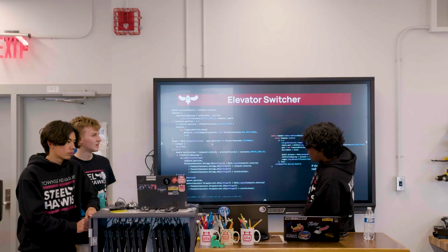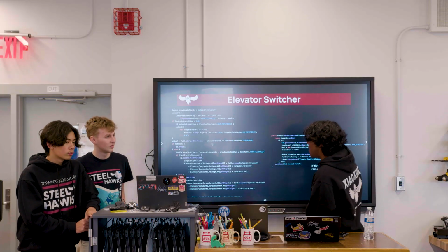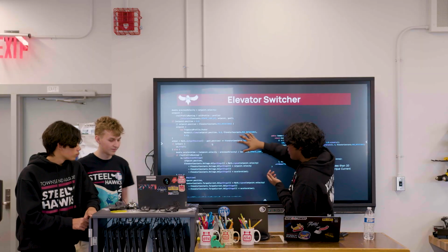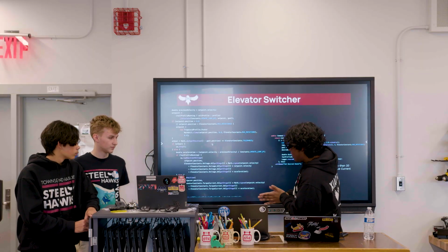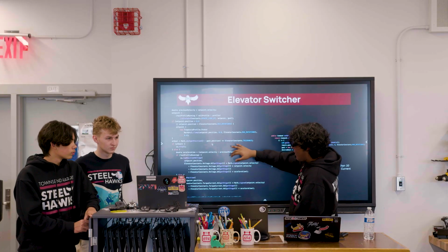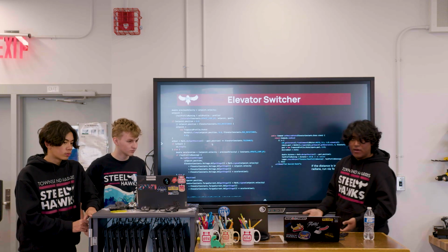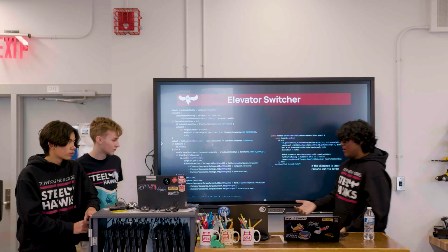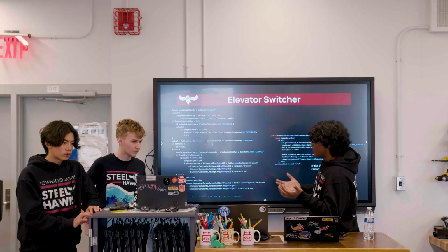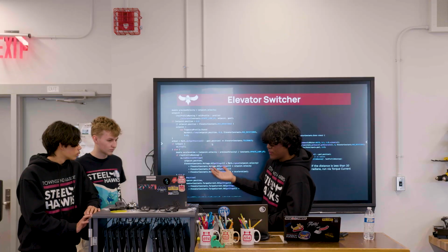Yeah, so we just check for that, and we go into our trapezoid profile at state, and we clamp it once again to make sure it stays between 0 and max rotations. This just checks if we're at the goal by doing get position minus goal position, and we take the absolute value to see if we're in the tolerance. This is nothing new. This is just like how you check for controllers at your school. So we'll ignore this for now. For at goal, we obviously stop the motors.